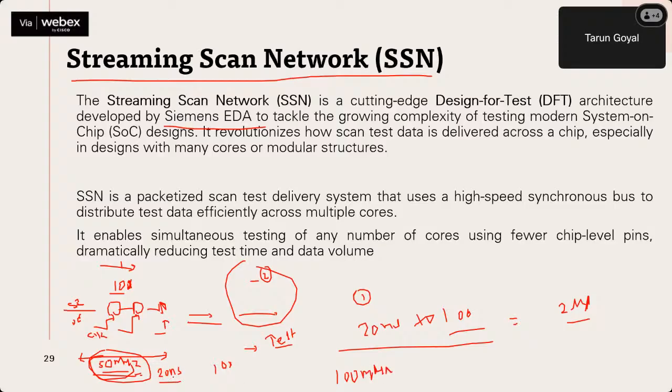Now what will be the time period? It will be 10 ns, and again 100 cycles. Then it will become 1 microsecond. What is the cost? Now you need to meet the design at 100 megahertz, right? Timing closure is required at 100 megahertz.